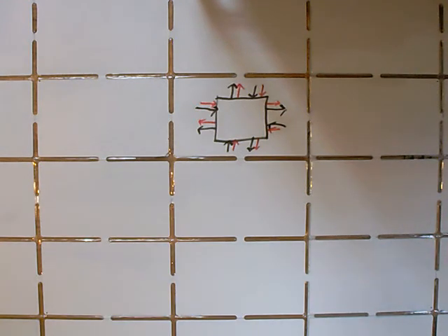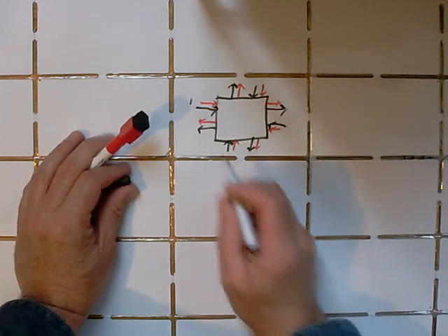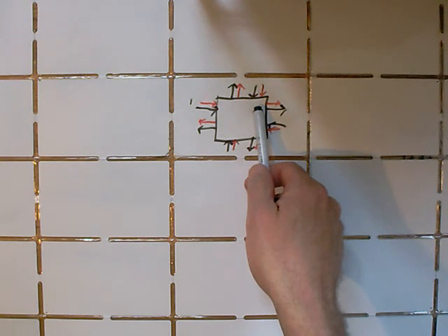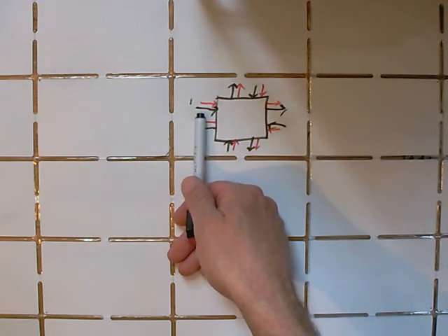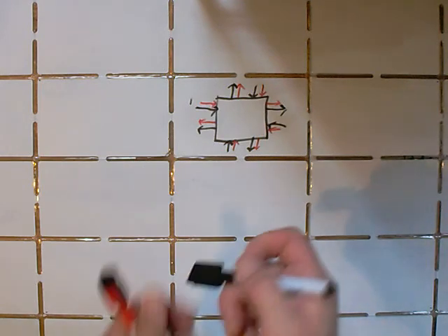And for the most part, we're not going to pay a lot of attention to the C lines, but there are a few operations where these are going to come into play. So as a very simple example, if I were to apply a 1 to a C input on this side, the cell enters C mode, and there's a system-wide clock, and every time the clock ticks, the next bit of the cell's truth table is going to be sent on this D output. And whatever bit is coming in on this D input will populate the truth table in the position of the bit that was just sent out.